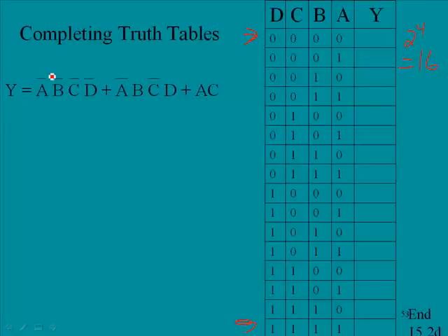And so the first one's real easy. It's going to be 0, 0, 0, 0. So we could get a 1 if we had all zeros input. And then we will get a high also if we have, let's see, this is going to be 0, 1, 0, 1. And if we flip it over to conform with that, we would have 1, 0, 1, 0. That is actually the number 10, 1, 0, 1, 0. So we should have a high right here.